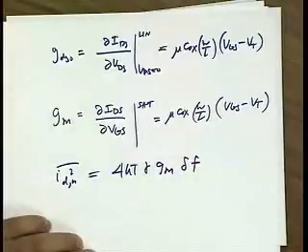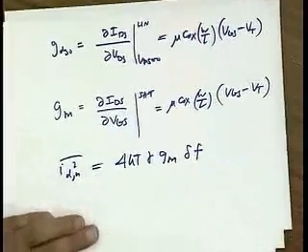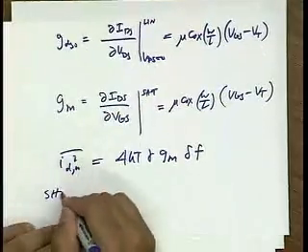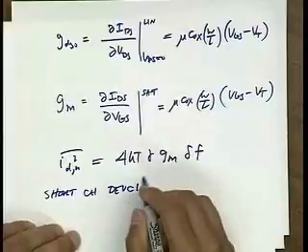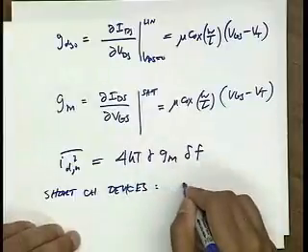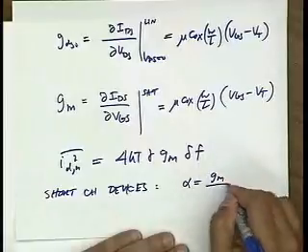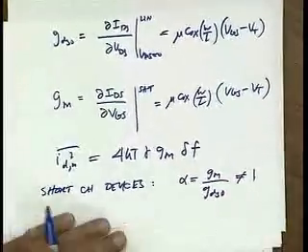Okay? Well, what's the problem with using GM here? Anybody? Short channel devices. Exactly. For short channel devices, we define a coefficient alpha, which is the ratio of GM over GDS0, and basically it's not equal to 1, as we see here.